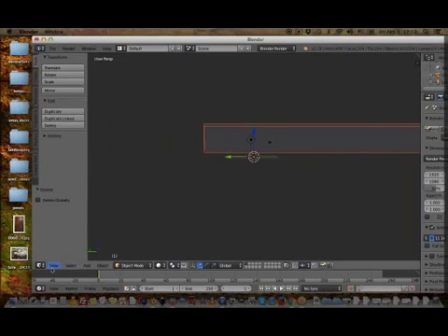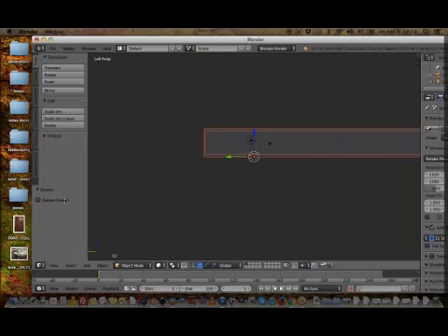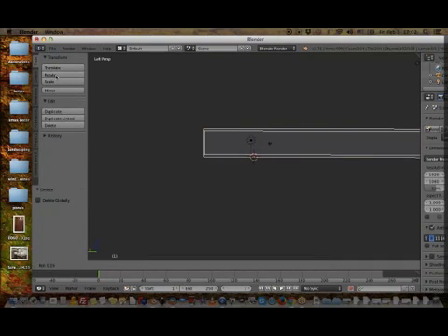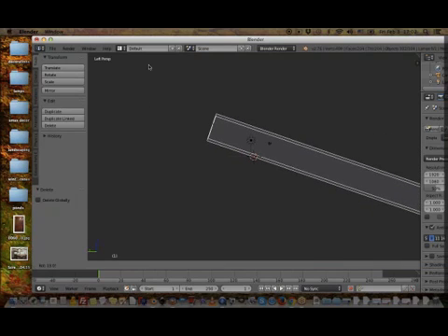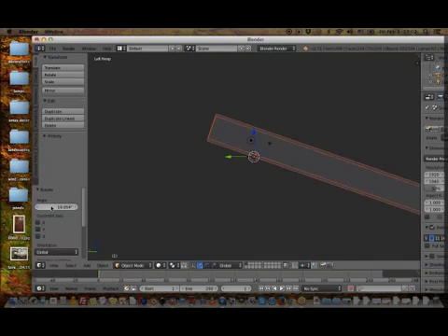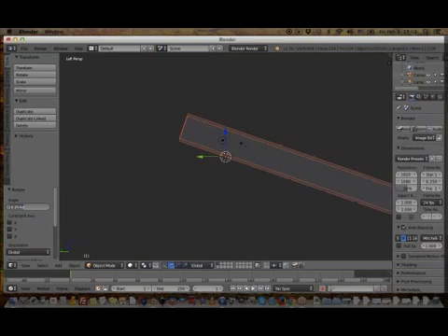Okay, here's my module. So what I did is I did view left, right? So I'm looking at it from the left angle. Now I'm going to do rotate, and I'm going to rotate this roof in whatever direction I need it to go. Okay, and you can enter the exact angle here. But of course, you got to know what the angle of your rotation is, and you do that by using a rafter angle calculator.